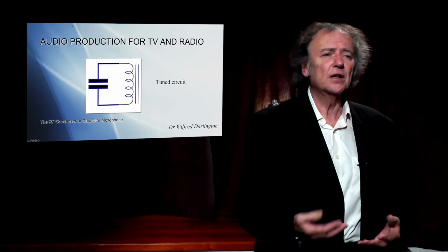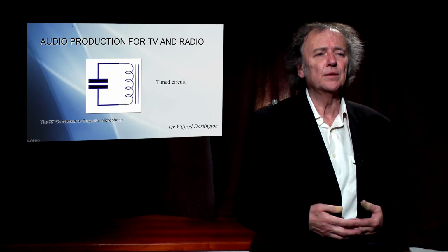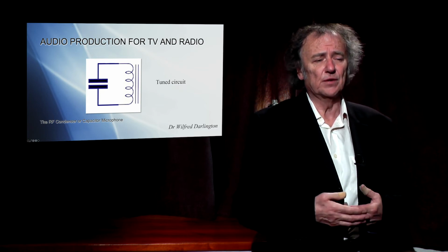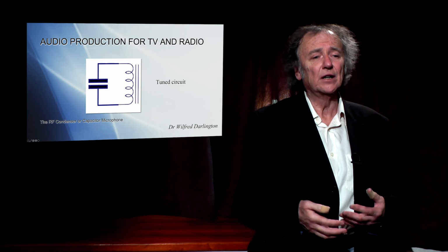You may be aware that if you connect a capacitor and an inductor in parallel, you create a tuned circuit. The circuit will resonate at a particular frequency. Let us say you choose values which result in a resonant frequency of 8 to 10 megahertz, say. 10 megs is well inside the range of frequencies which result in quite low impedance, friendly to amplifiers which utilize semiconductor technology, and well above the audible range.